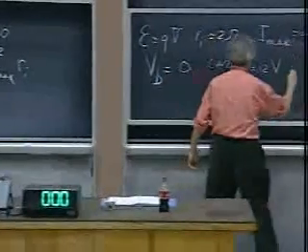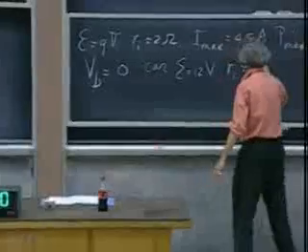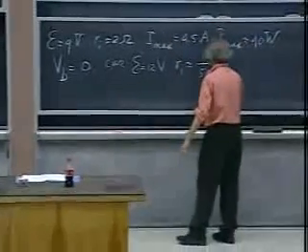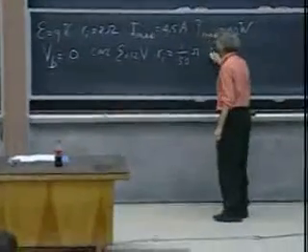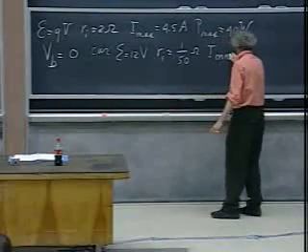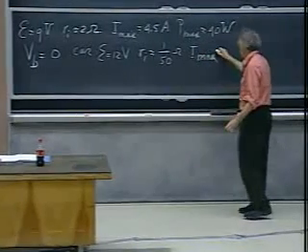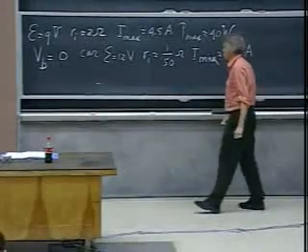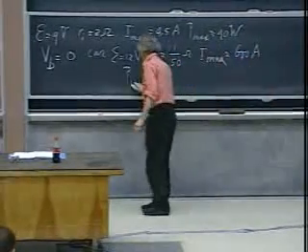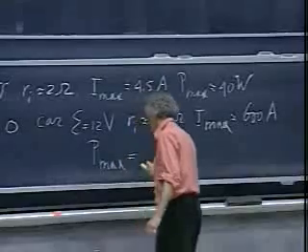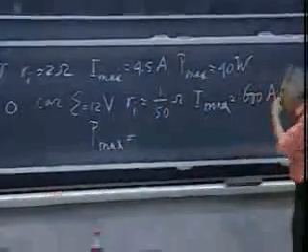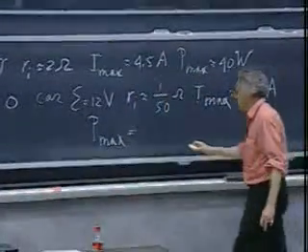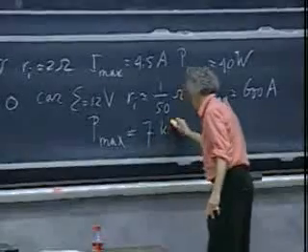It has a very low internal resistance of about 1/50th of an ohm. So that means that the maximum current that you can draw, if you would short circuit it, would be something like 600 amperes. And so the maximum power, if you were so stupid to short circuit it, that would all be generated inside the battery, would be something like 7 kilowatts.